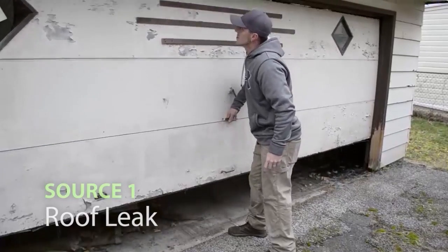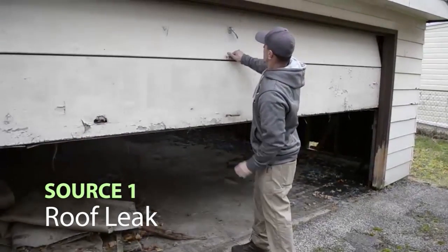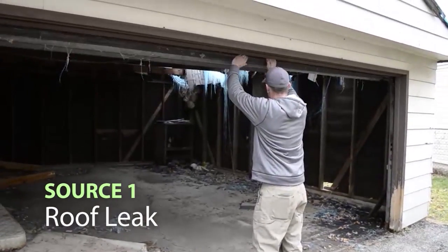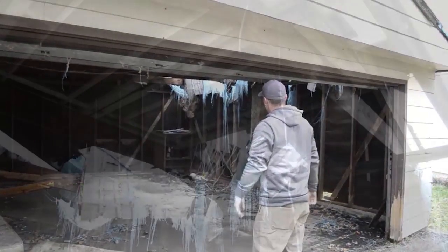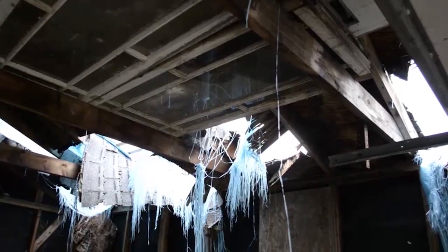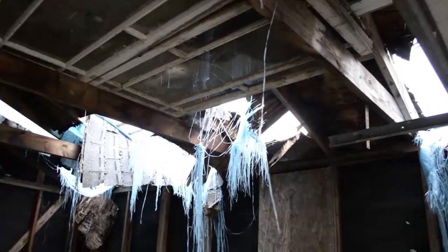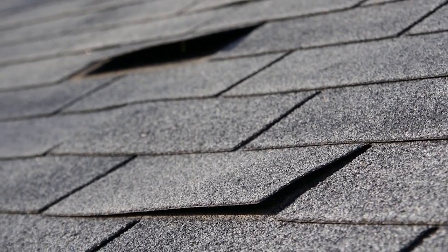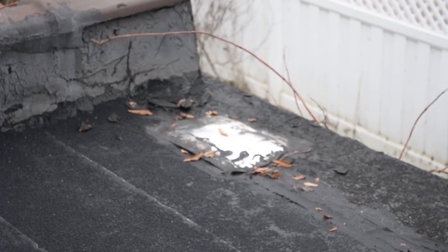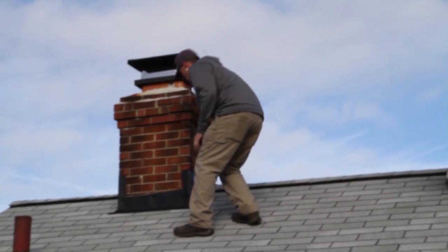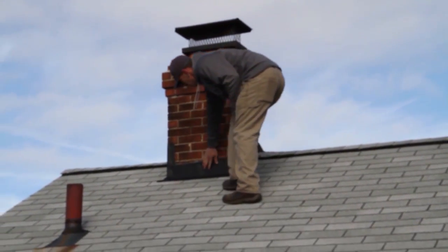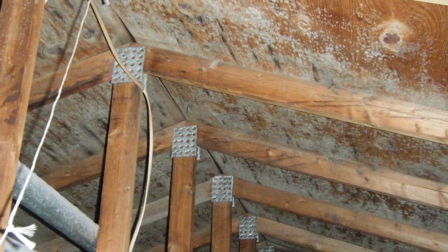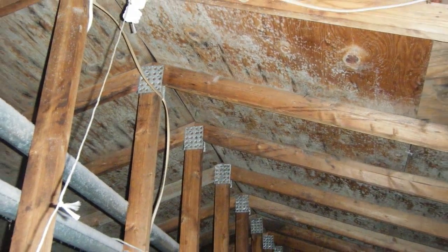Source 1 is a roof leak. An active leak is any condition where the roof does not protect the interior of the dwelling by way of water intrusion, potential water intrusion, or where missing roof components jeopardize the functionality of the roof. You should walk the roof to see if there is an active roof leak. Check for missing shingles and/or leaking intrusions. Also, check the chimney area by inspecting the flashing and overall condition of the brick, mortar, clay, and cap. Search for signs of sunlight shining through the roof from within the attic.